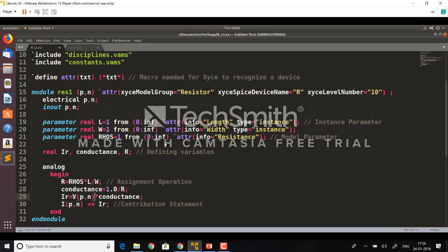Then what you need to know is these parameters. And how do you get these parameters? You take this model, you simulate it. Then you can change these parameters and your simulated results will change, right? For a given L, you'll have something, for a different L, you'll have something else. Then comes what we did before this, IC-CAP. We change these parameters, we try to match the output of this model with your TCAD data. That's what's called parameter extraction. We extract the values of these parameters such that this model behaves exactly like the device we are trying to simulate.